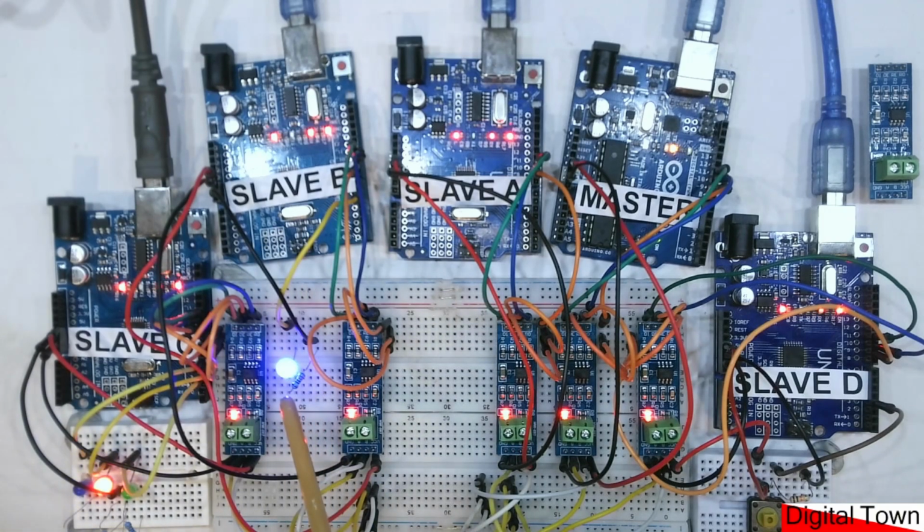At the same time, slave A is talking to slave C, and that is flashing the red LED on and off at a different interval. Slave B, which is driving this blue LED, is also controlling the blue LED on slave C. And finally, slave D, I just have a button down here, and when I press the button, the green comes on, and when I release it, the green goes off.